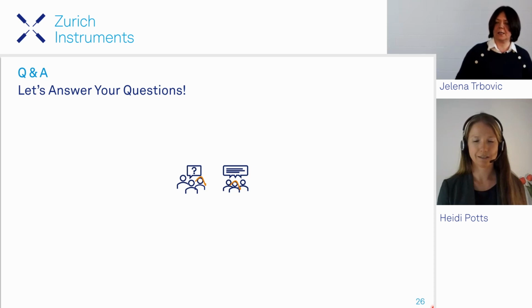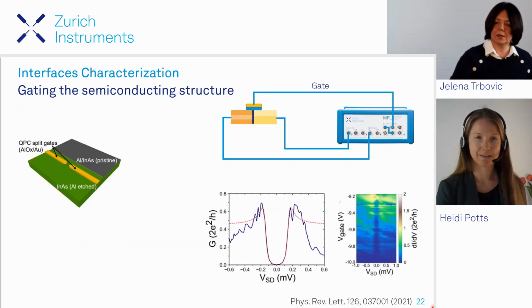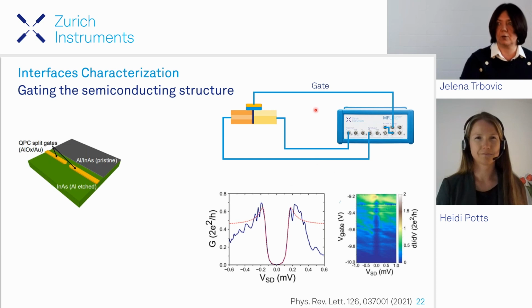Yes. Thanks, Heidi. That's indeed possible. So if I just go back a few slides, when I show this in a very simplified two-terminal, okay, this is already three-terminal geometry with a gate, but in this two-terminal measurement of the conductance, we basically have a DC bias applied and an AC excitation, and we measure the current here.